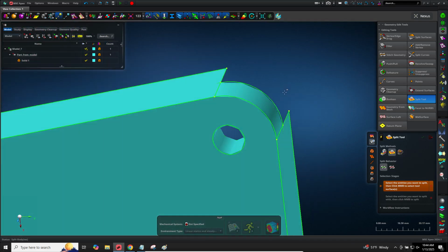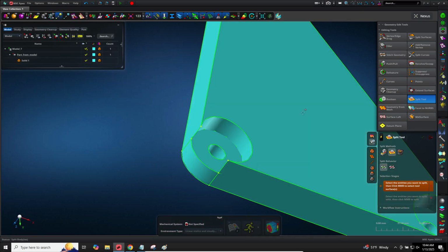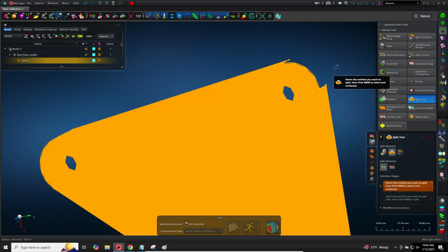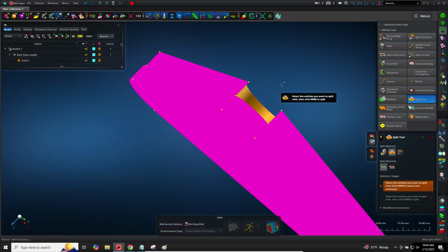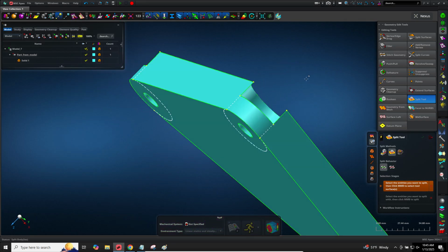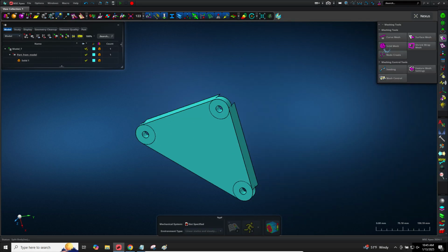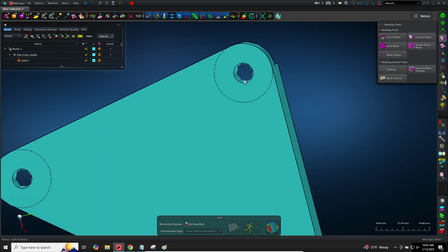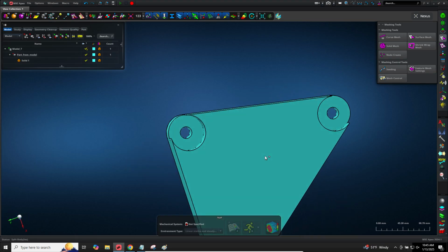So if you look on one side, there's no dotted line. One side is circular, but you can see that the opposing side is not similar. So extrusion will fail. Let's select this geometry, rotate this and select this face. And now you can see that I get a partition here on the other side. So when I go to the hex mesher, I now have these three circles, if you will. And on the opposing side, there are also three similar circles.